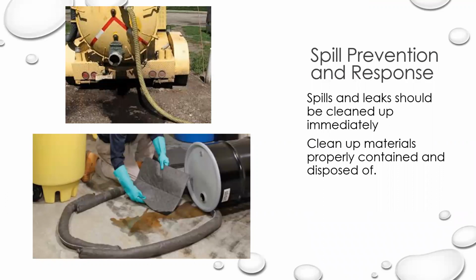All right, so the main thing also with this, it is important. It's a best management practice. As soon as the spill and leak occurs, it should be cleaned up immediately. The materials should be properly contained and disposed of. And again, that'll be in your waste or used oil containers unless it's hazardous. And in that case, you might have some additional issues, like you can't clean it up immediately, and you'd have to actually get your emergency response team in to deal with that kind of issue.